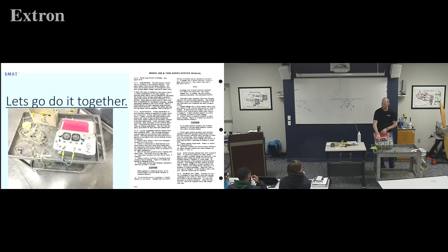There's a note, really important. You might think, if I really crank it down, I won't have a leak. You will wreck them. They're very highly tuned adjustable valves that you can have partial open, partial close. So just barely kissed close is fine. It will seal off. Please don't crank those down. They're really tight. So we've got a pressure and a vacuum. It's just a tank in the back of here.